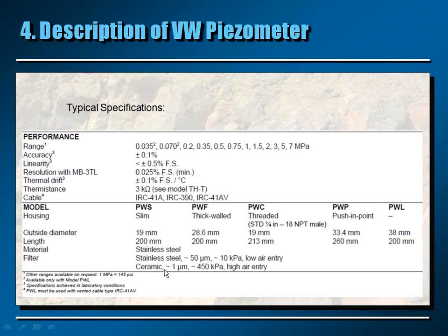So the ceramic filter won't let the water in easily. It is not as permeable. The ceramic filter was developed because over the years it was noted that in fine material, in clay soil, there was a possibility of fine migrations to the filter that would plug the filter.